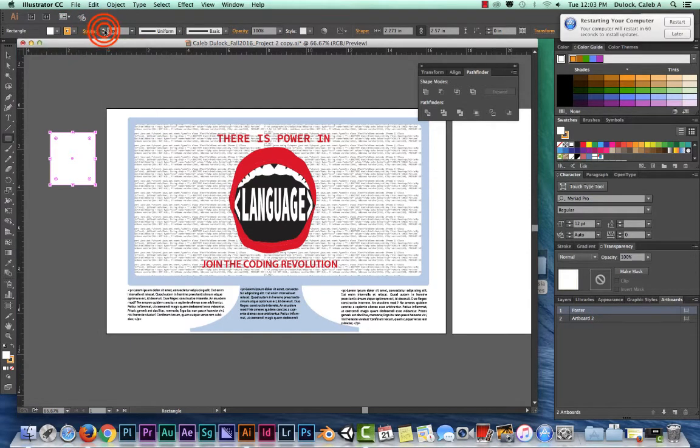Stroke lines can be converted in outside software, and if you're not careful, the shape or the thickness of them could shift. That's one property that you could lock into your design by converting it into an outline path rather than just an appearance property that pops up around the border of a shape. If you notice when I look at this rectangle right now, there's no pathway line that goes around the outer edge of the stroke. It's on the inside because it's marking the border of the original rectangle that we drew. The thickness of the stroke was changed, but it doesn't recognize it. So that's an appearance property that we would have to expand.